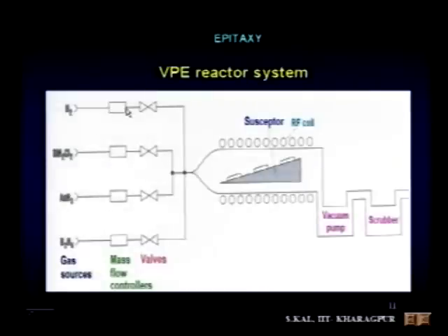So that carrier gas path is here, and these other two are dopant gases. One is arsine, AsH3, and this is B2H6, diborane. Okay, so you may have to grow epitaxial film with certain N type or P type dopant.